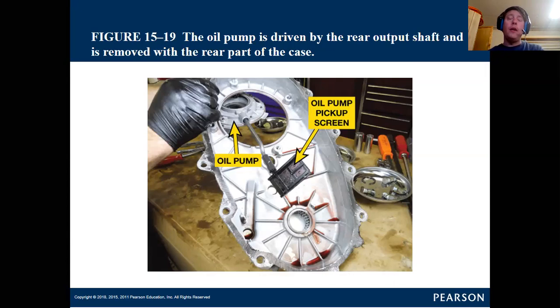So, for example, a lot of these GM vehicles that are the AutoTrac, I believe I'm saying that correctly, that's the auto feature, the auto button, take a blue fluid. It's literally blue. It is not red ATF. If it is the non-auto version, it does not take the blue, it takes the red. And there's a special part number for that.